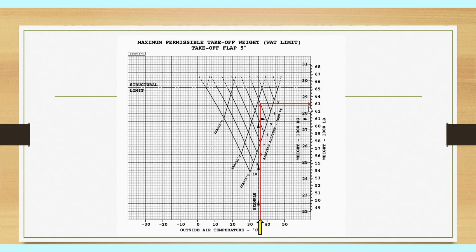That's 28,600 kilograms. So 28,600 kilograms is our maximum takeoff weight on this particular day with these particular conditions. Okay, excellent. And remember, our weight is still less than this one. So we can take up to this. You remember the Lilongwe one, we just shot all the way up, but here now we can't, our maximum isn't the structural limit maximum. It is something else, because that's where the AFM is telling us to stop our calculations.